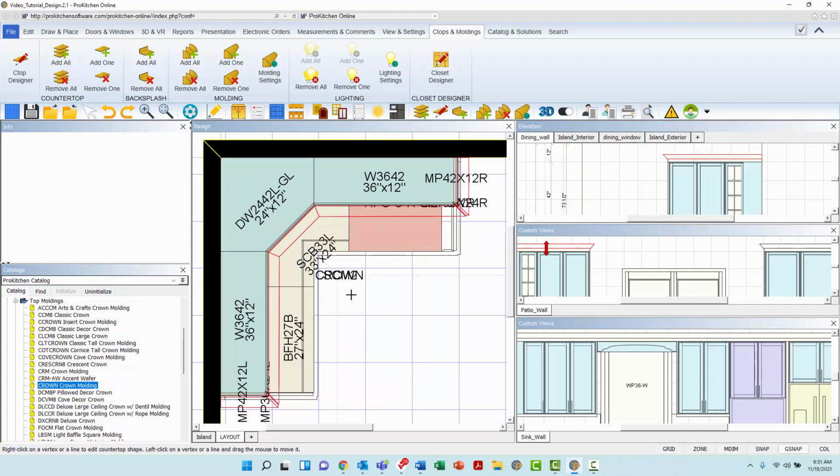If, when moving a point, you end up crossing one line over another, creating an unrealistic shape to the molding, you may hover over either of the two lines, right-click to open the subset of tools, and select Intersect. This will remove the intersection of the two lines at the cross point and provide you a new shape to diminish or expand.